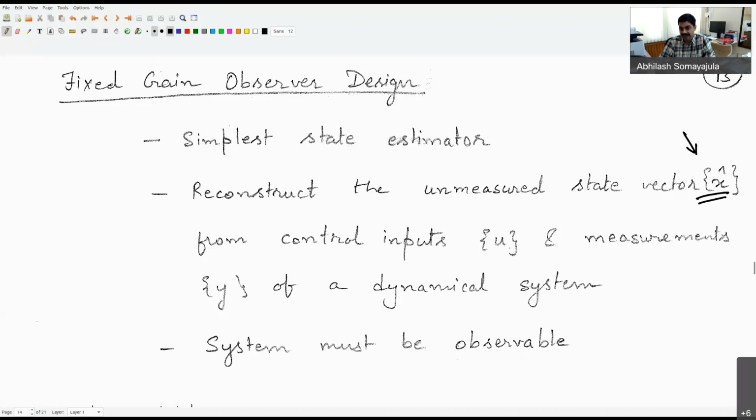Let us say now you have a LiDAR from which you're trying to figure out your localization. You may be able to figure out the X, Y, and Z point of where you are, and probably an orientation angle as well, but it cannot give you velocities per se. If you have a DVL, Doppler velocity log, then you may be able to get velocity estimates out of it, but it will not give you position estimates. So please understand that each different sensor will be at any one time measuring a part of the state space. It will not be measuring the complete state space.